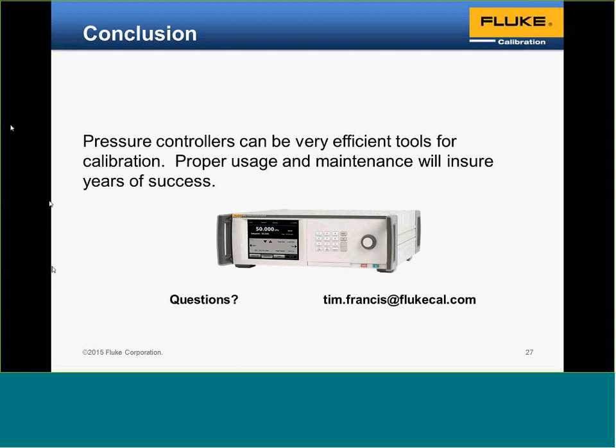Stabilization capability is also always recommended. Make sure that you allow things to stabilize before taking readings, in situations where the device under test receives pressure slower than the other one, so you have everything stabilized before you take your readings. And again, if using software, it's always best to take multiple readings and average.